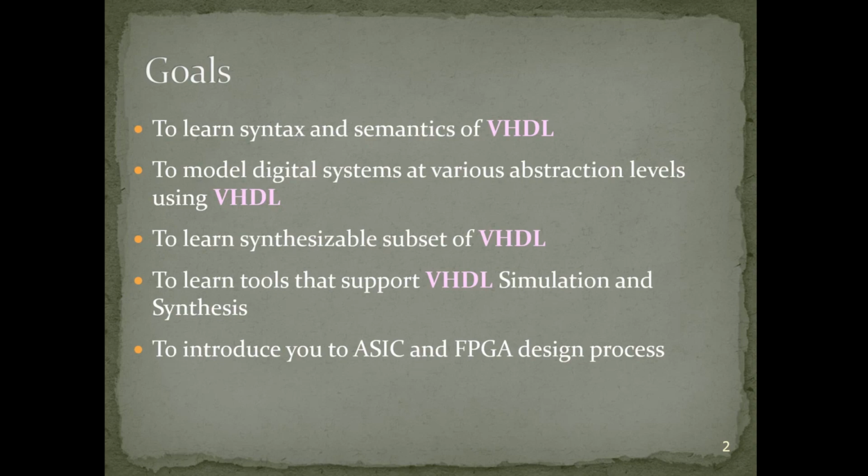But any hardware description language essentially has a subset of instructions which can be used to synthesize stuff, so essentially to run that code on hardware. But there are also some instructions which cannot be used for synthesis purposes. Their job basically is to assist, for example, with simulation or with other aspects of the environment.